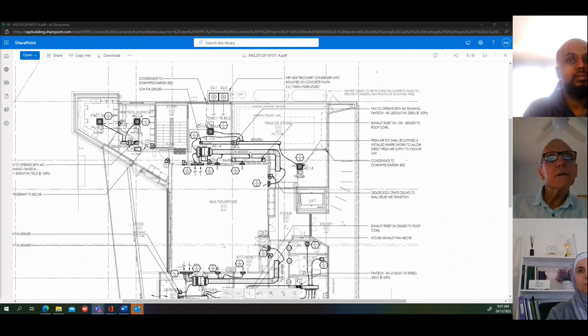Yes. So if 450 by 300, as shown on the design drawing, is the correct size for the airflow, then we have to maintain that. But the sheet metal will be bigger because of the internal insulation. So is that clear to you, Jella? Yeah, I think I understand that.